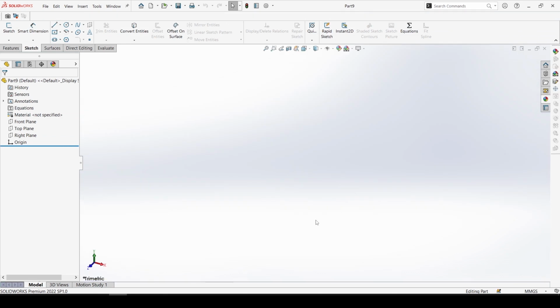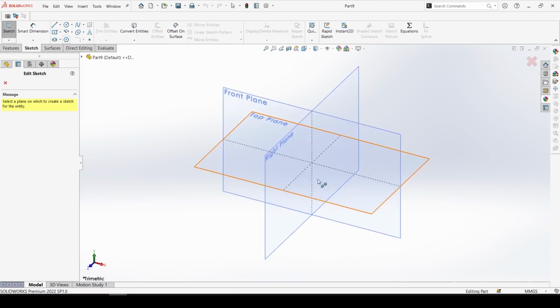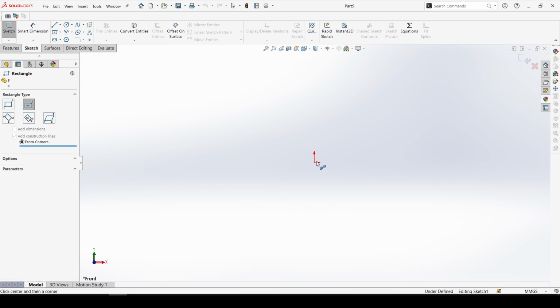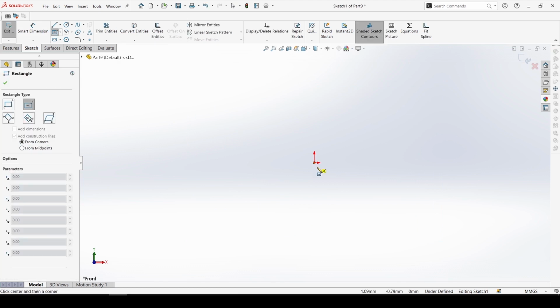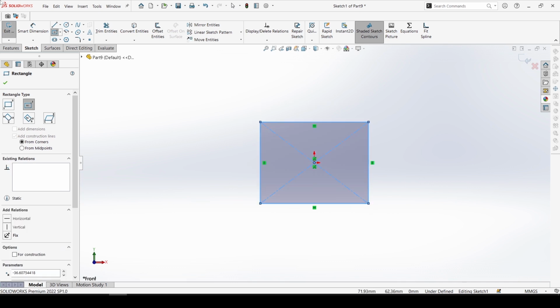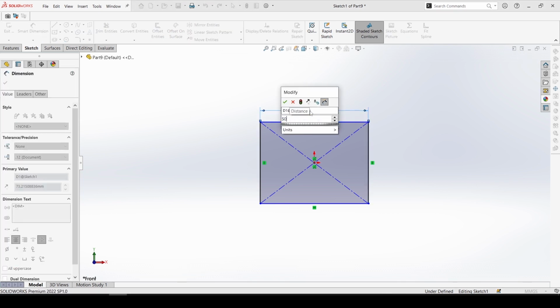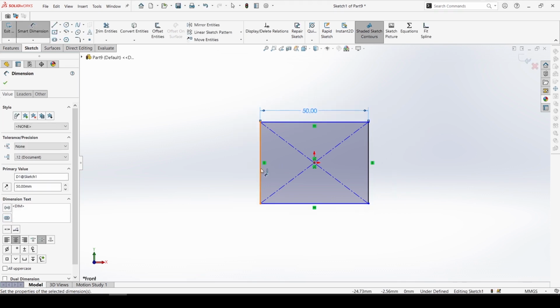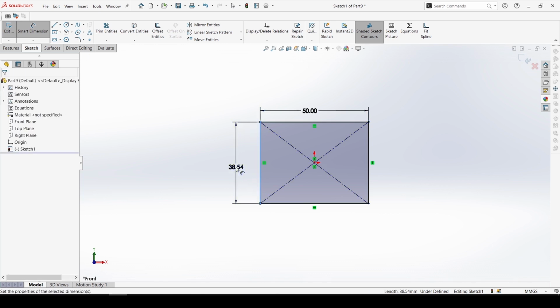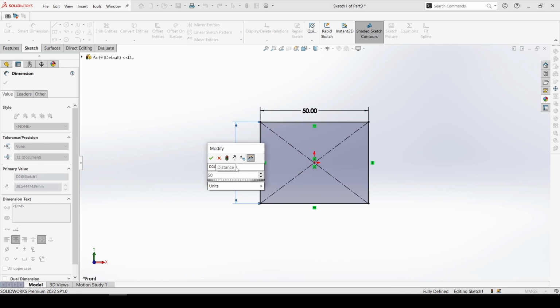I'm going to first create a 3D object which I will use explaining to you like most of features in this SolidWorks interface. Let me create something simple like a cube on the front plane. Apply some dimensions. Let me give like 50 millimeters. Enter. You just need to click on this line and slide a little bit, then enter dimensions, then hit enter.